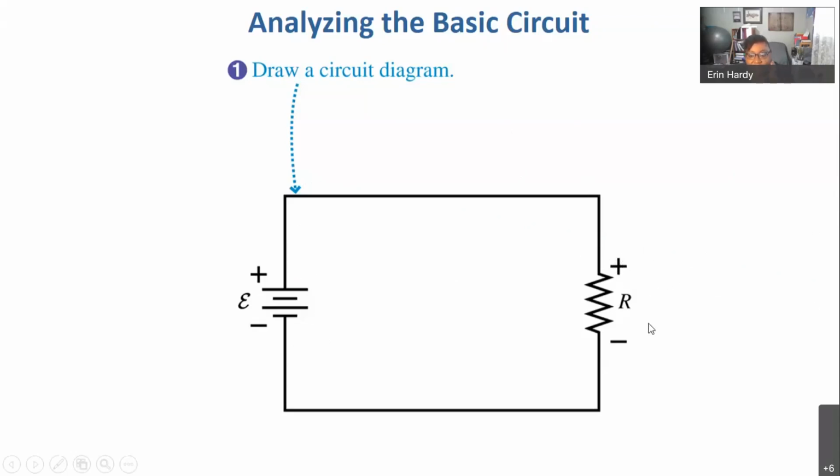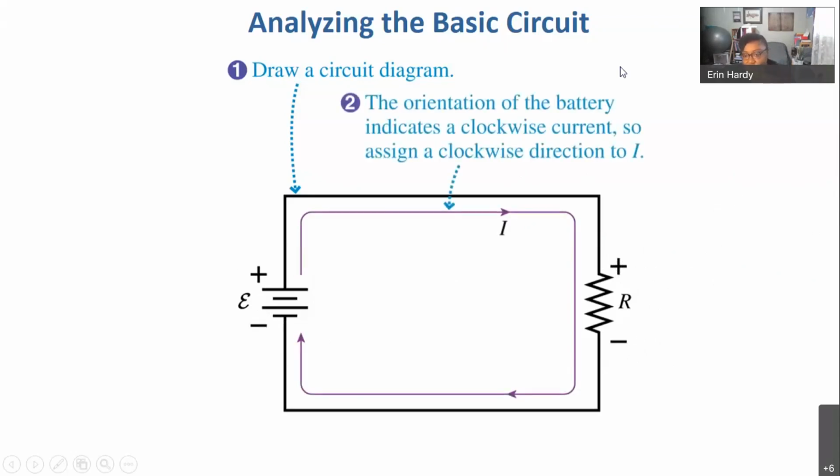So when a charge carrier goes from positive to negative, my delta V is going to be a negative value across here, whereas it's going to be a positive value here, because I am, maybe jumping the gun, assuming that the direction of current that I've guessed is going to be heading clockwise. And in this case my guess is a good one, because I'm just tracking the direction of positive charges as we imagine them moving through this circuit.